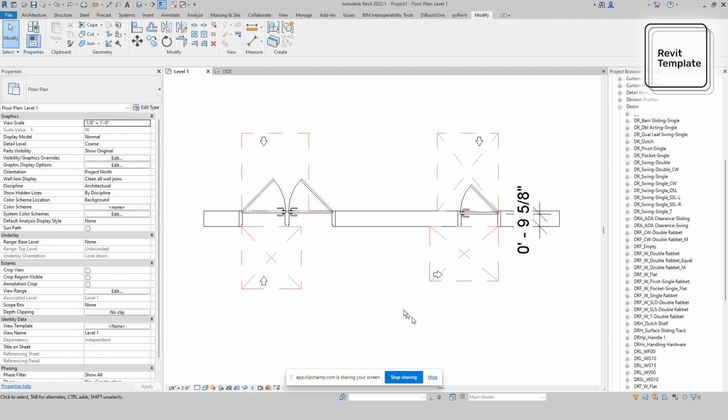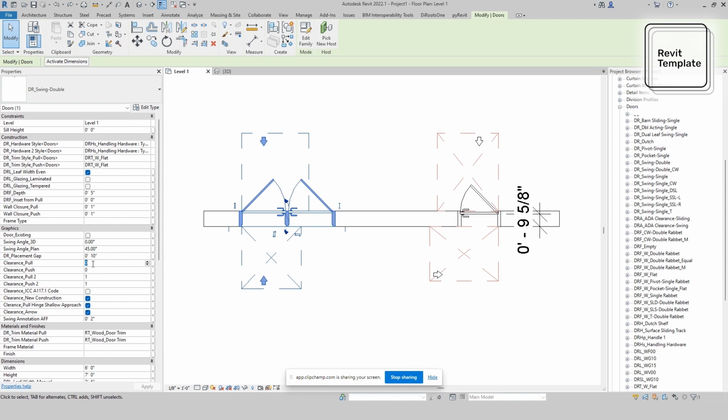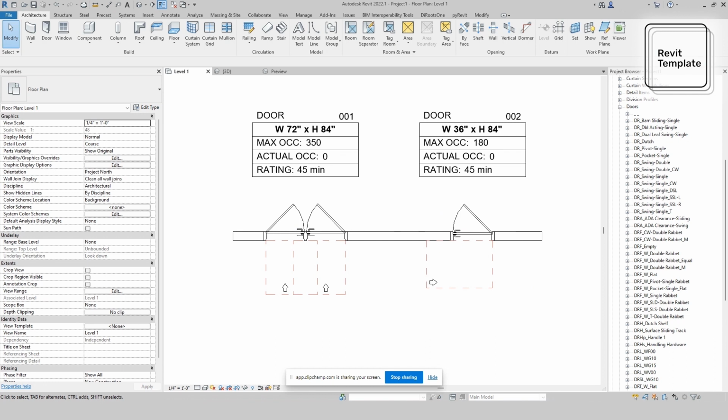Clearances also adjust and verify individual leaves in door assemblies. As users can see, we have clearance lines appearing in both door leaves, as well as indicating whether each leaf individually complies with code minimums. This will enhance for more powerful and better life safety analysis and also translates into egress calculations.